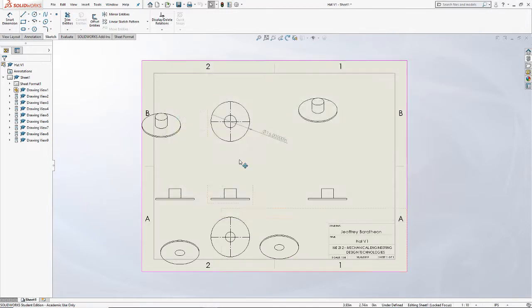Your drawing files should have enough information that someone could recreate the part from your drawing. So you're going to be applying dimensions, and you're going to be applying enough dimensions to fully define the part. Most students have a default inclination to try to over-define everything, applying dimensions everywhere. Remember, you only need enough dimensions to fully define the part. You don't need to have every dimension listed everywhere because you don't want to create conflicts in your tolerancing.